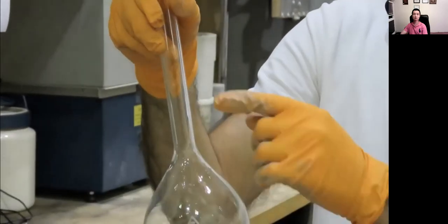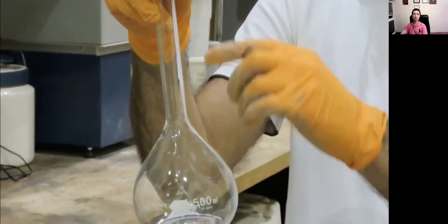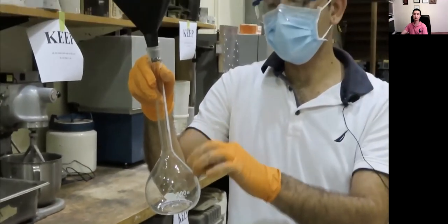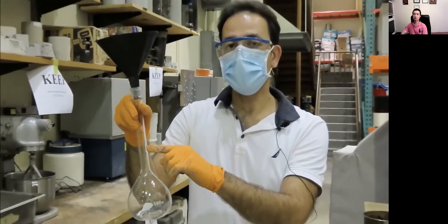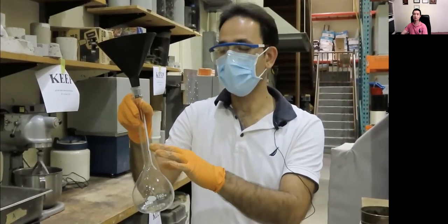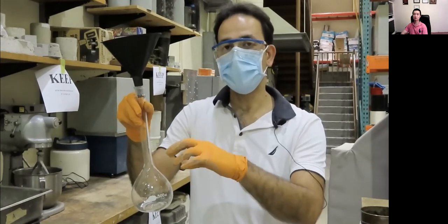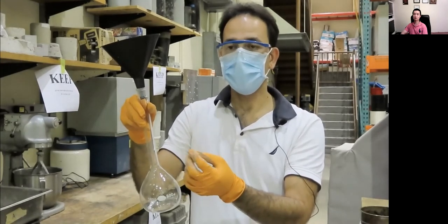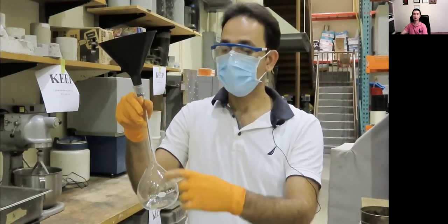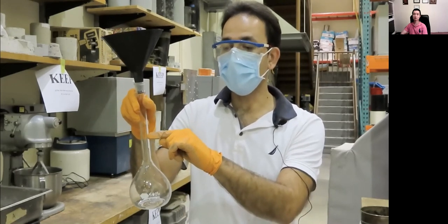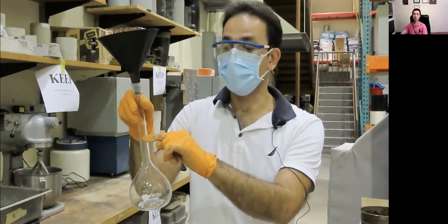milliliter. But when I introduce the fine aggregate inside the water and then add more water, there might be, absolutely, some air bubbles entrapped between the particles of fine aggregate. I need to get rid of them first and then get right on the number, right on the mark.